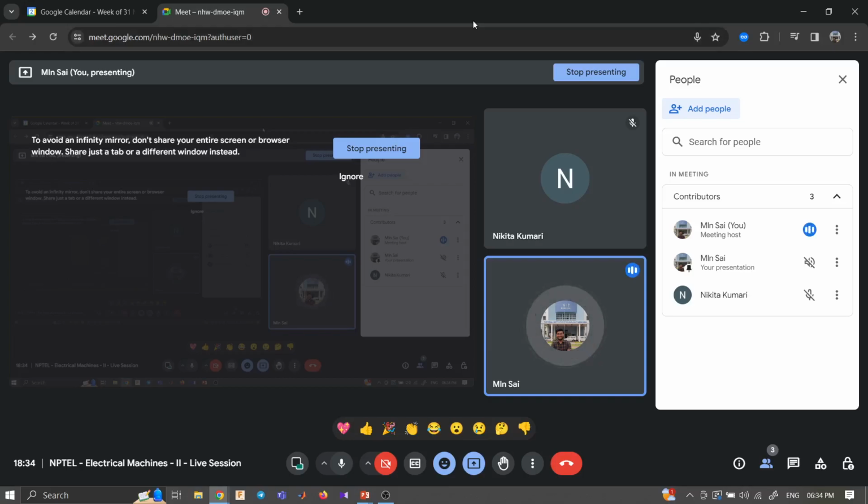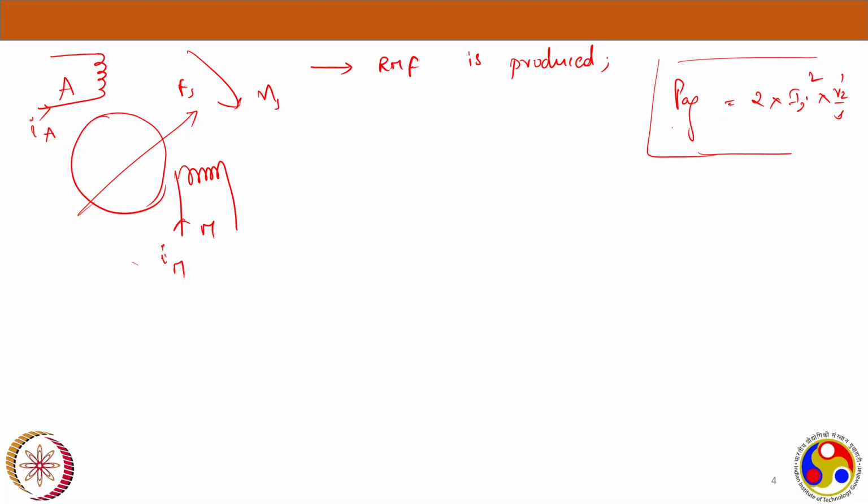Now all your different analysis will be similar from now. Since three-phase is the supply which is generally available, that's why these three-phase induction machines are very popular, which we discussed before. Now, if we have a two-phase balanced induction machine and we want to run it, we require a balanced two-phase supply, right?